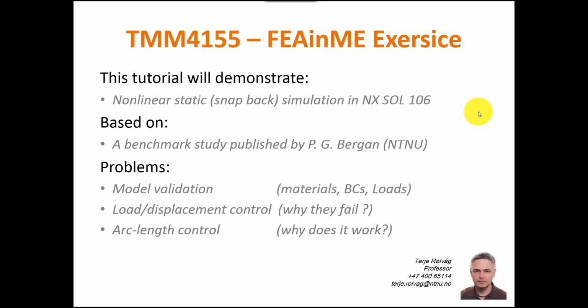Good morning, everyone. I'm TJ, and today I want to show you a nonlinear static simulation in NX SOL106. It's a snapback of a cylindrical shell, which is a tough numerical challenge to the solver. And I will use a benchmark study published by P.G. Bergan.